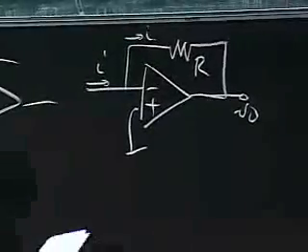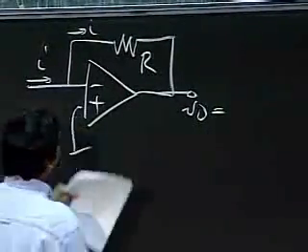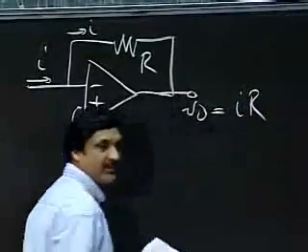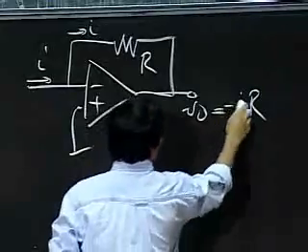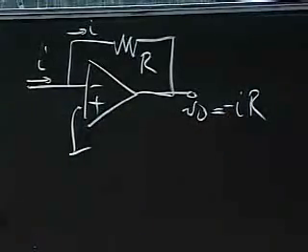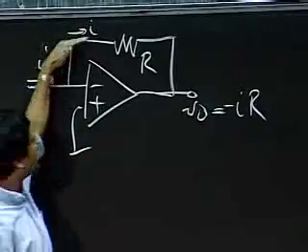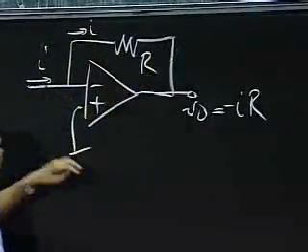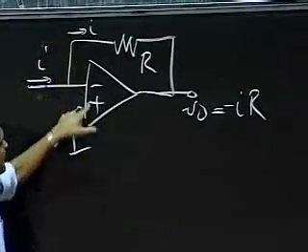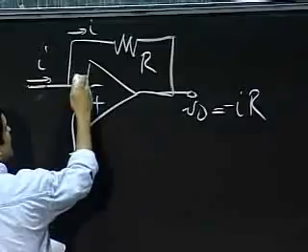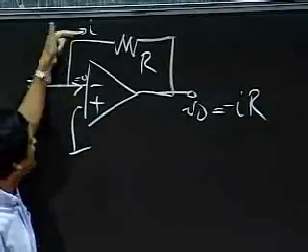If I stick a resistor in there, what is VO equal to? So VO is simply IR, right? Yeah, that's right. Okay? So VO is, I get I here, so the I pumps through here. Remember, what comes in here must get reflected up because the current going in here is 0. So all the I must come out here.